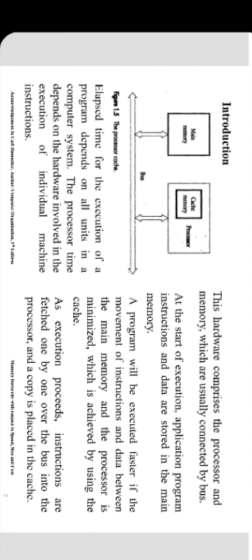And in the figure here, one more memory is shown, cache memory. Each time the processor accesses main memory, the access time will be larger. Hence, execution time is more. We say that processor performance is poor. To increase the speed of execution, some part of memory is implemented on chip with the processor.